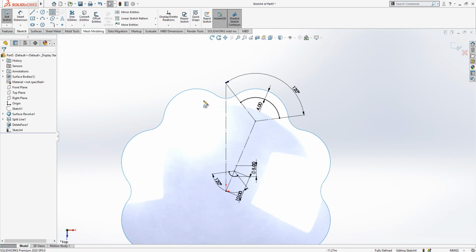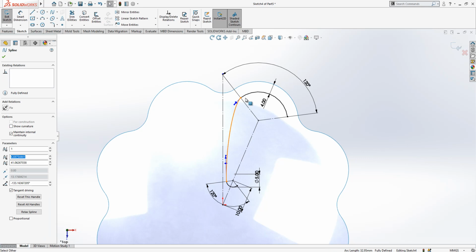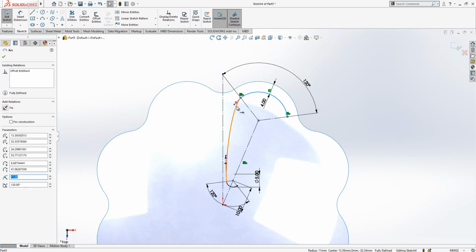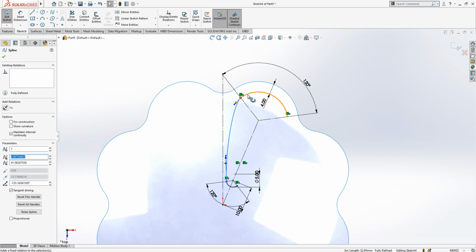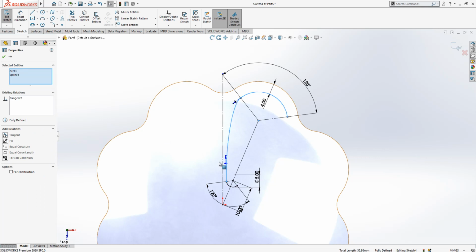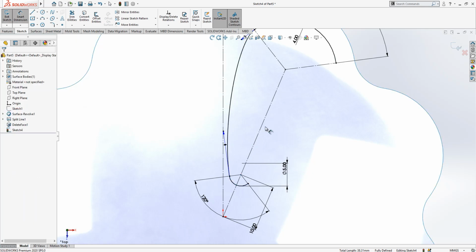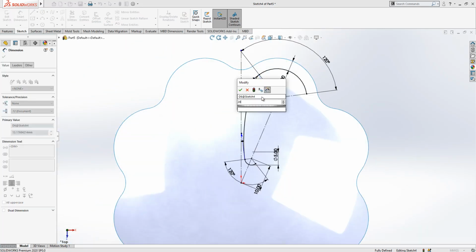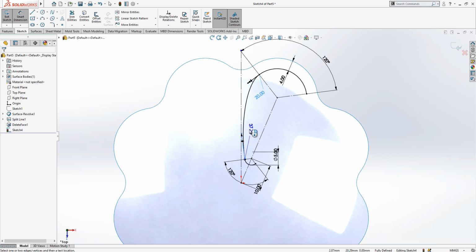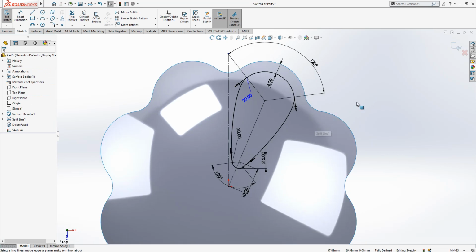And then later on a spline between two objects. We create a spline. I'm playing with them a little bit. Here I press my Control while it's pressed. Again, I will select two objects. Select 1, 2, tangent, and this one again tangent. And then the last operation, giving our tangency value. This is 20. This is also 20. And then making a mirror about this axis. That's good.